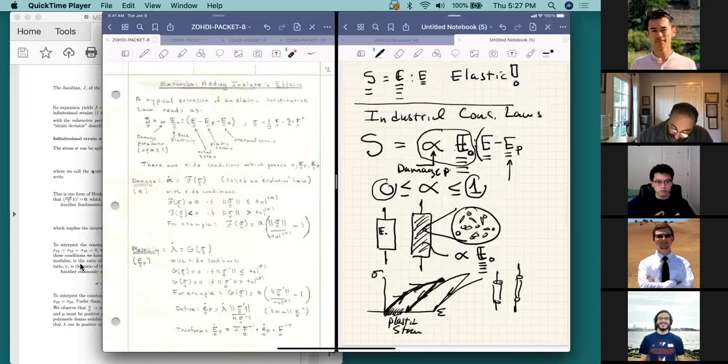And so you start to have this weird ratcheting behavior where every time you deform the material, it starts out from a new permanent deformation state. So if I pulled on this material and I stretched it, and then I let it go, it would shrink back down to probably this size, but it wouldn't be the same size that it originally was. It'll be a little bit bigger. That amount is in fact exactly equal to this plastic strain.